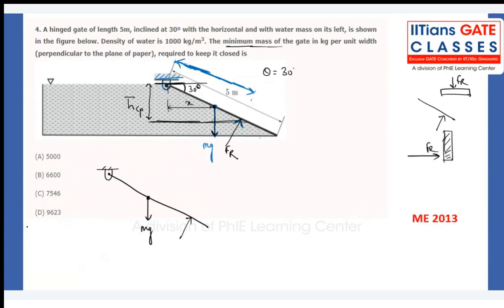Now, this is what we have done in the calculations, and what is the hydrostatic resultant force formula? That will not change based on the orientation being changed from vertical to angle theta. Again from here also, rho g into h bar into area, right? So when you try to calculate from here, what is my rho? That is 1000. g is what? If you check, 9.81. H bar. What is my h bar? That is a big question.